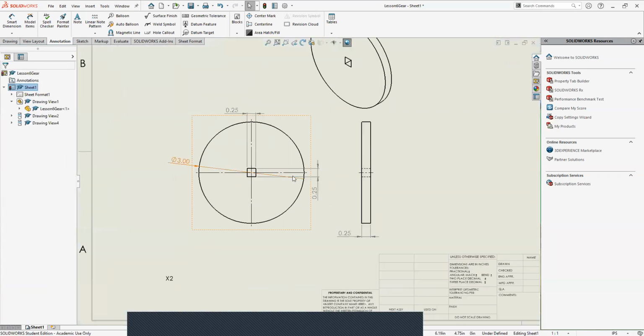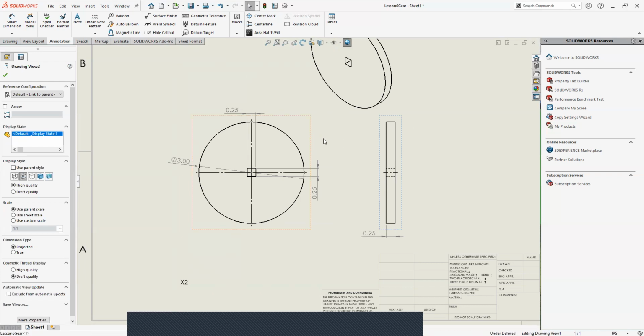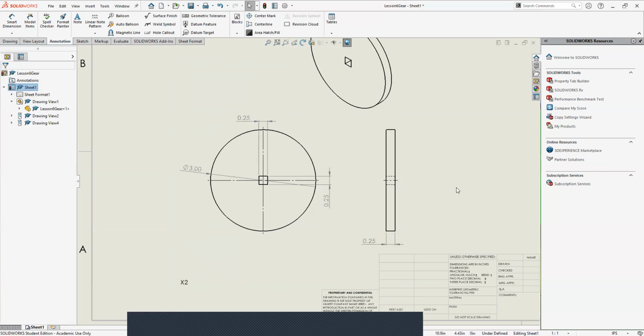What I always, so when I did TAing for a class that did drawings, I mean, make sure you're following your rules. Like, don't go too crazy on hidden lines if you don't need them, because sometimes they can get very confusing. So be careful with those and make sure you're not dimensioning to them. Be careful to make sure that all of your views are projected after your first view, if you're working with the same model. Obviously don't dimension to hidden lines.